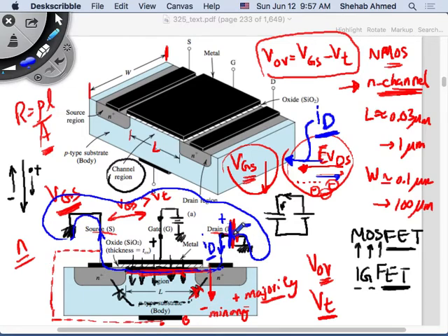We have voltage in the drain and in the gate. Only when I apply it. Because if I don't have voltage between the drain and the ground, of course, I have to have a voltage at the gate that is beyond the threshold voltage, right? Because that's what created this whole thing. That's what brought all the free electrons to the top.